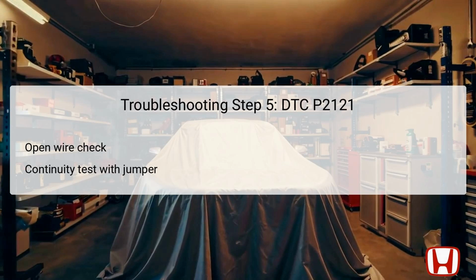Next, they perform a continuity test designed to detect any breaks in the APS1 wire between the PCM and the APP sensor. A successful outcome should show continuity. If so, it confirms that the wiring is intact. Conversely, if no continuity is detected, it points to an open circuit that necessitates investigating the wire path for potential damage or disconnections that would impair the operation of the sensor.